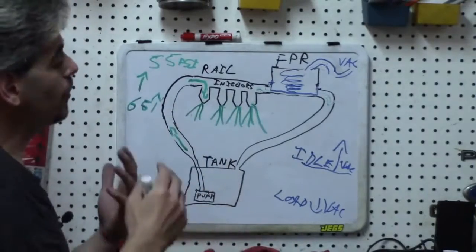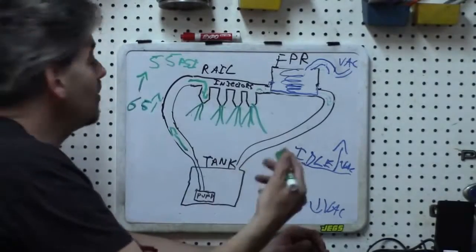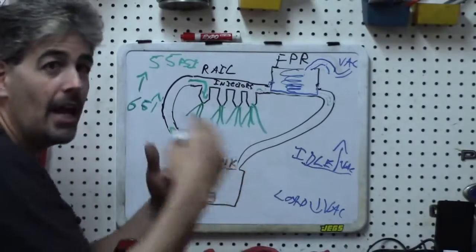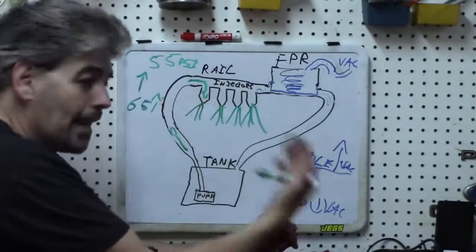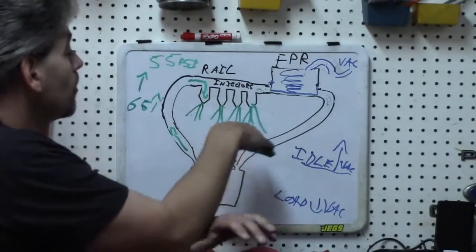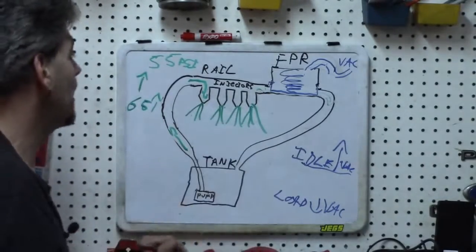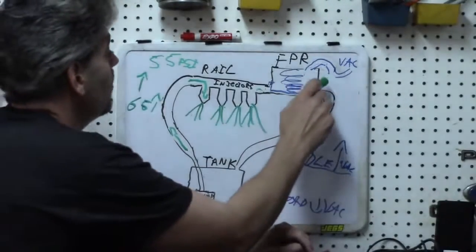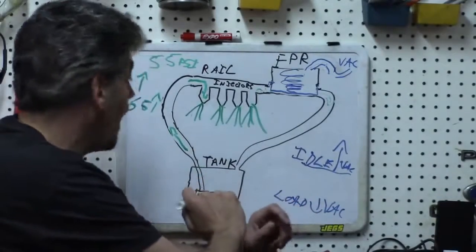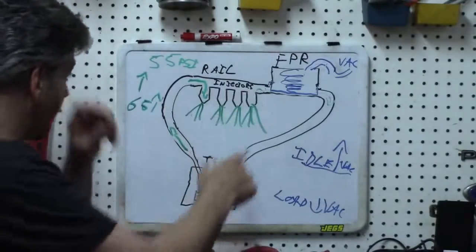Now, most of you guys who are experts in fuel trim realize that that rich condition is going to be compensated for when detected by the O2 sensor, so the pulse length will be conformed so that we get a better air-fuel mix, and the short-term fuel trim will eventually level off. But the long-term fuel trim is still going to show that rich condition, and almost certainly you would throw a check engine light in this condition. So you would look and see that you have a vacuum leak in the hose as maybe one of your first steps. What's another very simple way that you could validate this as being the issue?